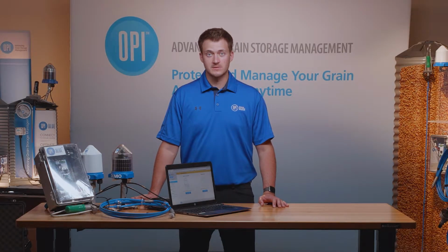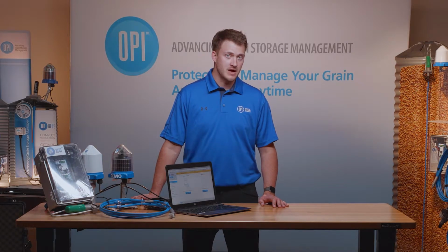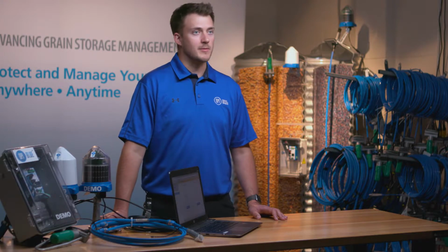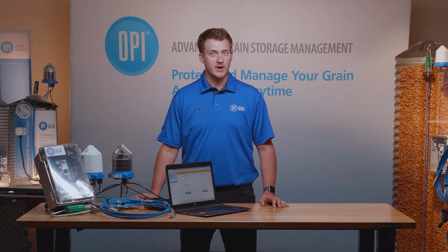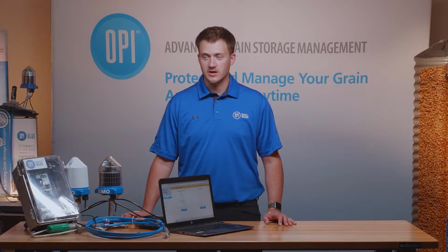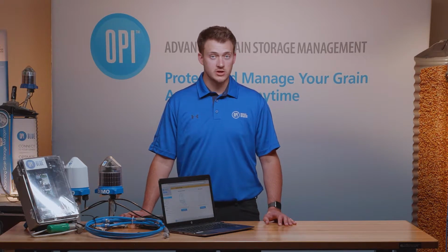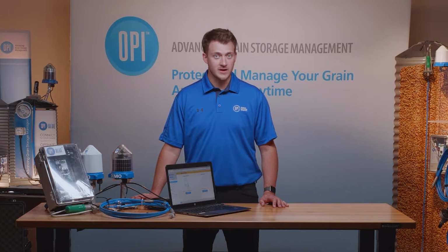I work for OPI Systems, and today I'm going to show you how to set up a site on managegrain.com. This typically happens after installation of the gateway and all of the cable nodes. So I will demonstrate how to register the gateway, register the cable node, and map the cable node to the gateway. Additionally, I will show how to create a bin structure and map a cable to the bin structure. This is all on managegrain.com. You should be able to log in and get started.